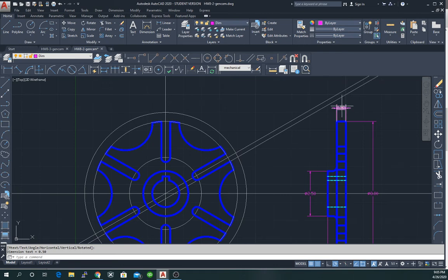Now, if you notice here, the 0.5 is on the inside, and that's related to one of the settings we set up. So what we can do is just move that to the outside, like so. So what we had to do is click on the inside square. On linear dimensions, you always have a marker for where the dimension is. On radial dimensions for circles and arcs and things, it's a little more tricky. Okay, so now we have all that done.